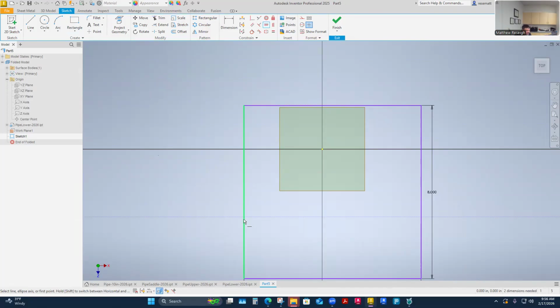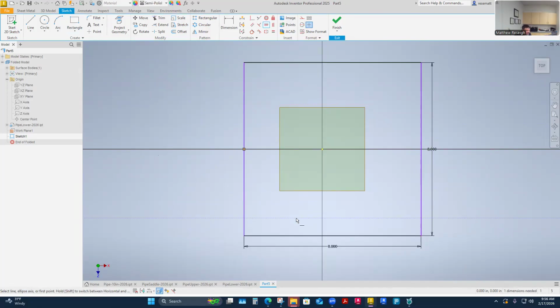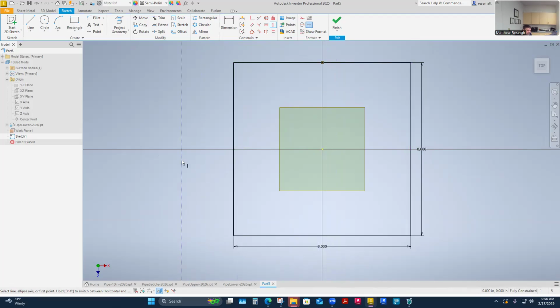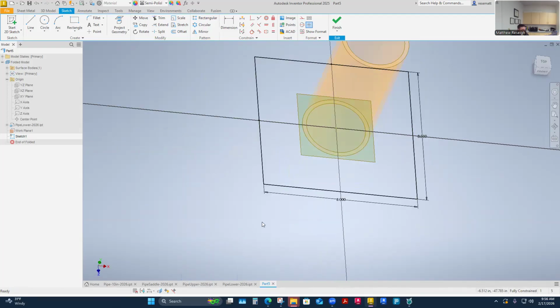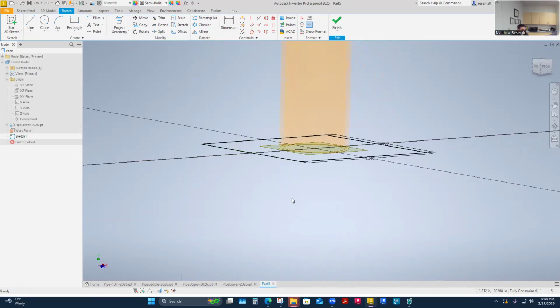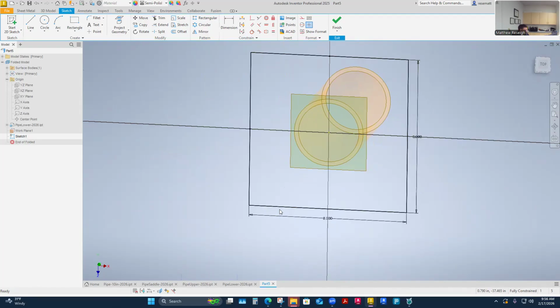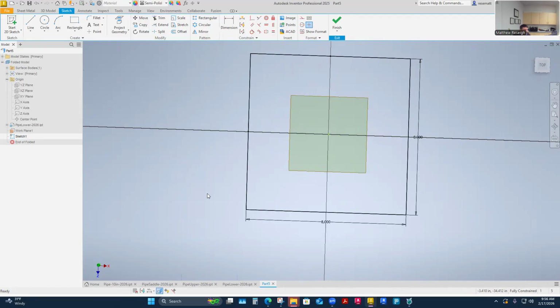However you want to do that, I like to do this kind of stuff this way, where I pick a midpoint. You've seen me do this a lot. There's my midpoint, horizontal, constrained to that. It doesn't push those points together, it just keeps them in horizontal alignment. Same with this vertical one on this midpoint. So this is the way I'm centering it over my part, which is how I want my part to sit there if I slice my graphics, right? And I'll extrude this down a 1/2 inch thick. I'll F7 slice those away though.